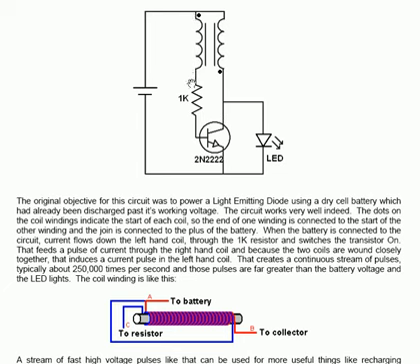And that extra pulse in the first coil is fed through the 1K resistor into the base of the transistor and switches it on, which powers the second coil, which induces a current in the first coil, which flows through the 1K resistor into the base of the transistor and switches it on. That generates a considerably higher voltage at the collector than is given by the battery.